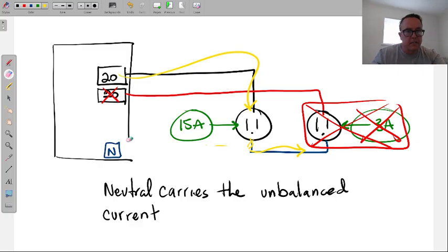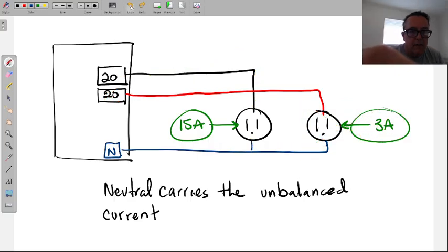Working on the line, disconnected one breaker, want to take some wires apart, want to disassemble this circuit and do whatever to it. And now I've created a situation where I'm backfeeding current into an outlet that the electrician thought was off, and now potentially they can get shocked. And of course, amperage is the part that will kill us. So this is where simultaneous showed up. If you want to shut one breaker off, you shut both off at the same time.